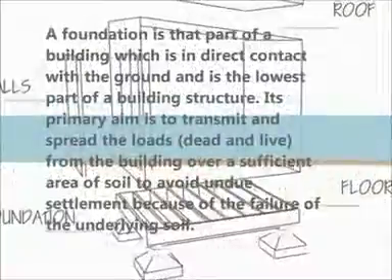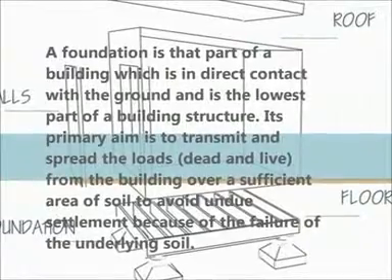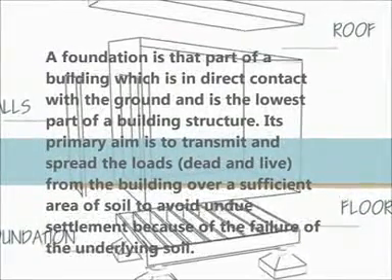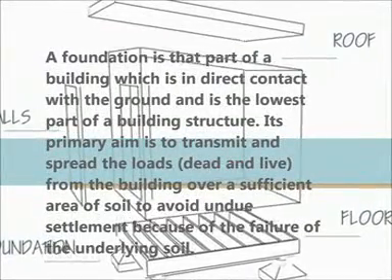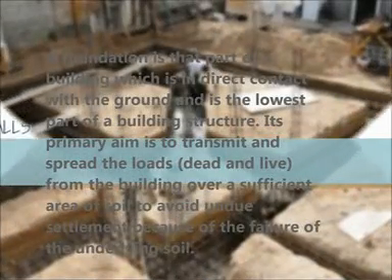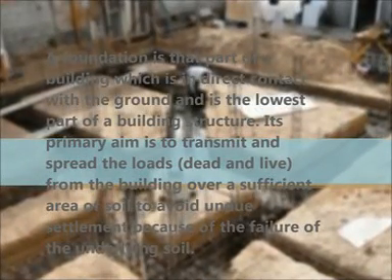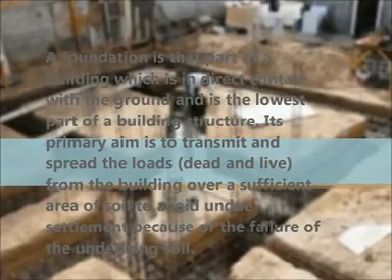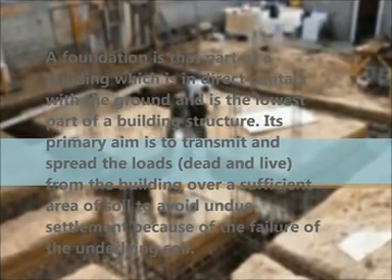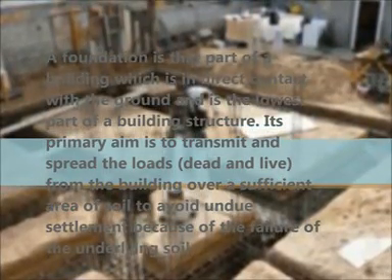Foundation. A foundation is that part of a building which is in direct contact with the ground and is the lowest part of a building structure. Its primary aim is to transmit and spread the loads, dead and live, from the building over a sufficient area of soil to avoid undue settlement because of the failure of the underlying soil.